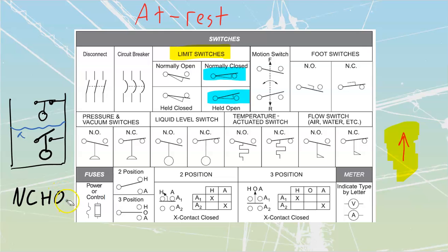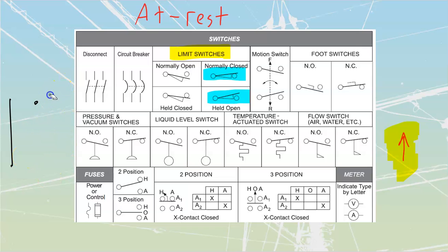Okay, you're going to have to remember these things later on once you get into some motor control, particularly in pumps. You know, it's really commonplace. People want to have stops as normally closed, but the problem is your stop is usually going to be at the bottom of the pit, because that's what you're doing if you're pumping water out of it, but it would always be held open and stuff. So you have to sometimes refer to these things when you're actually looking at them in the field.